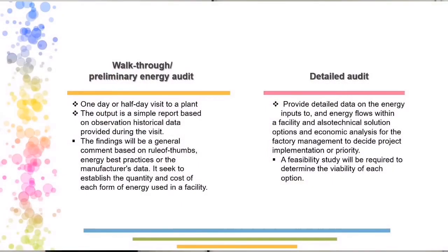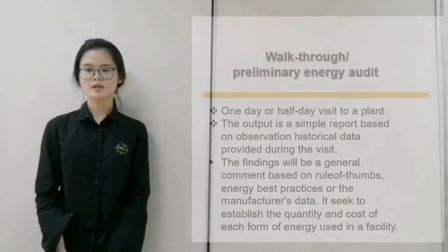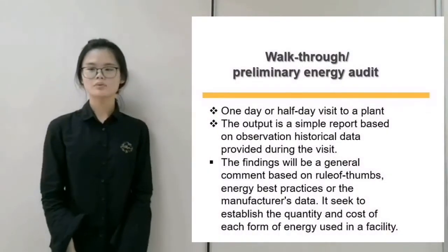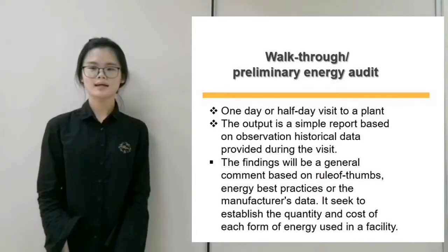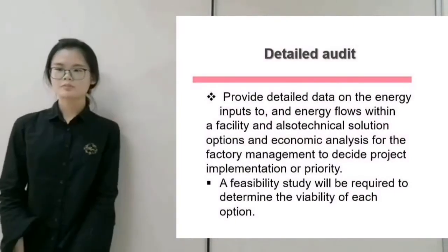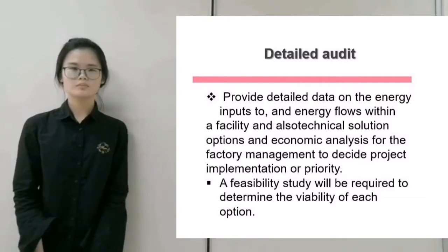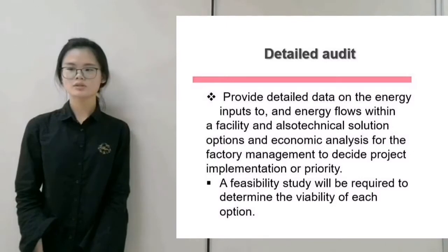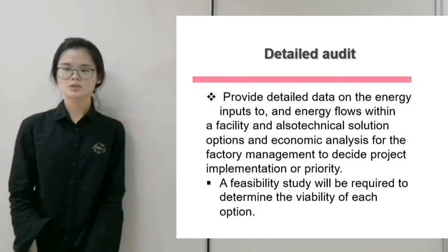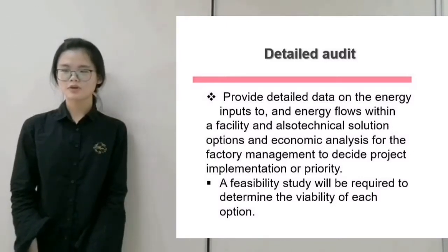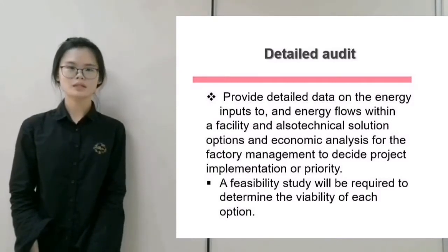The walkthrough is usually carried out in a 1 day or half-day visit to a plant. The output is a simple report based on the observation and historic data provided during the visit. And the detailed audit provides detailed data on the energy input and energy flow within a facility, and solution options and economic analysis for the management to decide on project implementation.